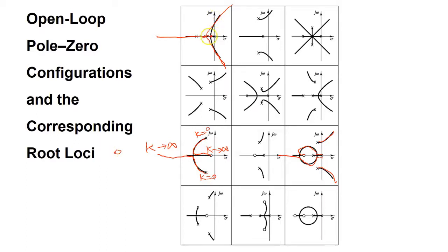What about these cases? We are starting at 3 poles, but all of them are going to what? When k goes to infinity, this branch is just going, this branch is just going, and this branch is just going. Where do they go? Should I end up at a 0? Yes, but all of the zeros in this case are imaginary at infinity. So if the number of poles and zeros is not equal, which most of the time it is not, whatever we are lacking, we assume they are imaginary at infinity. Let me show you one more example, and then we go back to the breakaway and break-in points.